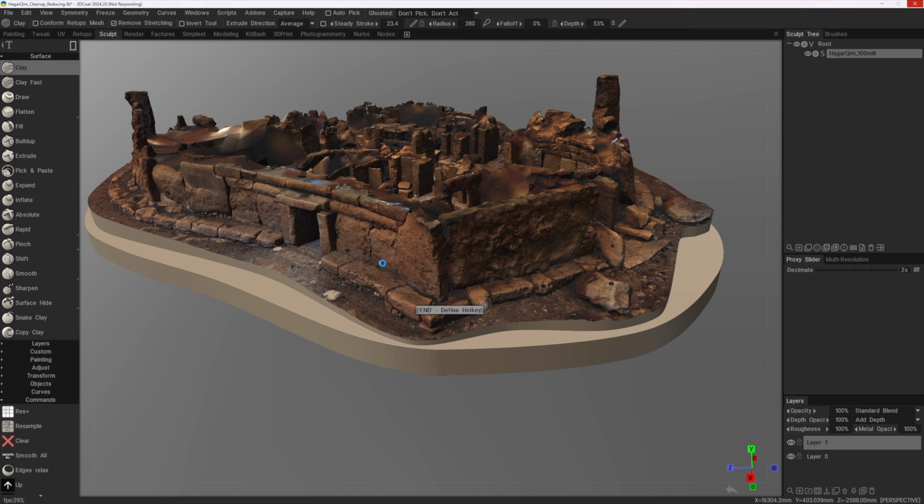And the only reason for that is that in RealityScan, it's a bit tricky to get things back in because of the coordinate system. It always flips around. And if you import the full mesh before you're sure you got it right, well, it will take quite a long time before you get it in. So exporting a very low res just to see if you get the position right is kind of recommended.